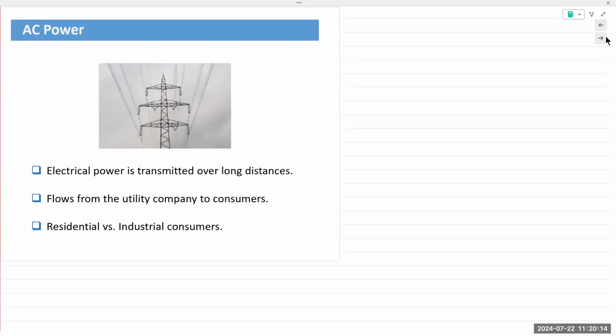When we studied resistors, power was simple. Whether it's DC or AC, resistors behave exactly the same way for both. V equals IR, Ohm's law. P equals VI, the product of voltage and current. For a resistor, it would be I squared times R, or V squared divided by R. For an inductor and a capacitor, it's just not quite as straightforward.